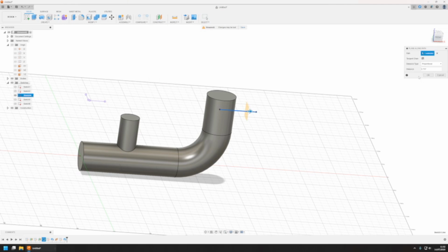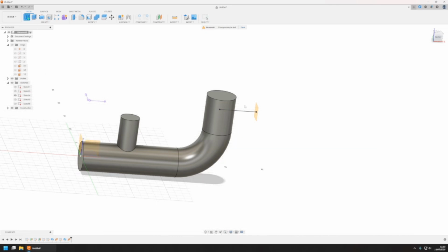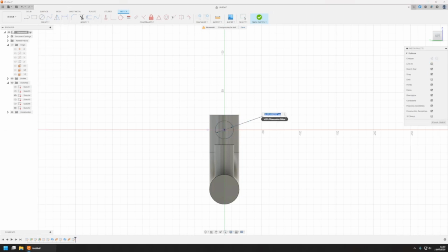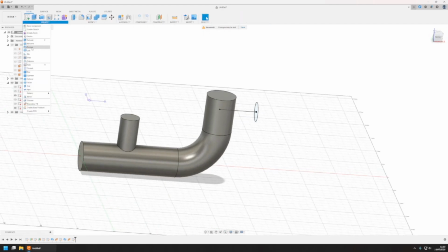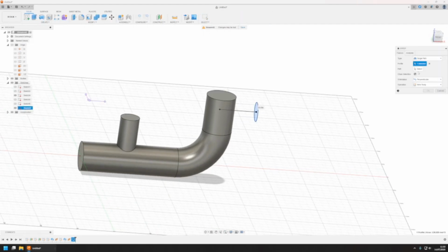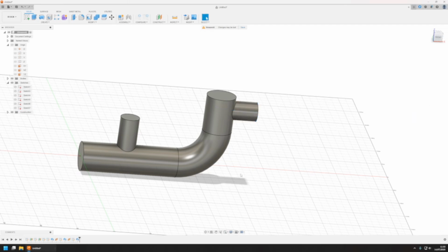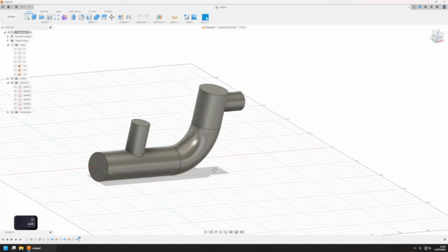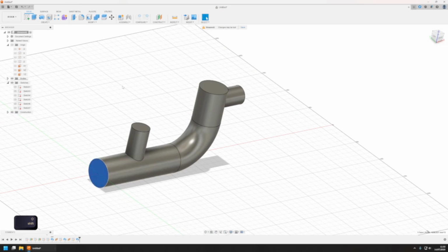You should be pretty well versed in doing this now. Create a plane, create a sketch, create a circle. Dimension the circle, finish the sketch, and create the sweep. Join. Okay, perfect. So that's fine. This is really shaping to look pretty much like our part.